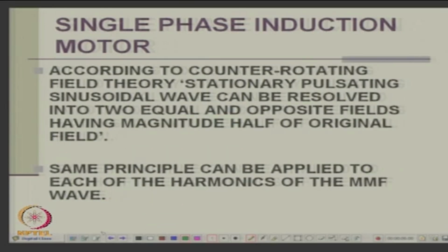Therefore, we also know that the MMF that is produced will be resolved into forward and backward fields with equal amplitude and opposite direction. Again, do not get confused, field can be both a flux or an MMF, right.